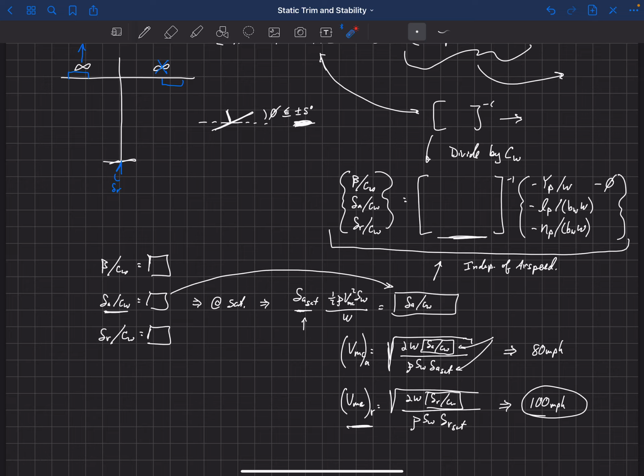This is maybe a little bit counterintuitive, because most of the time we're trying to get rid of weight on an aircraft because that's associated with drag, so to increase performance you usually want less weight. Well, in this case, to get a lower minimum control airspeed and less deflections, you actually want more weight.